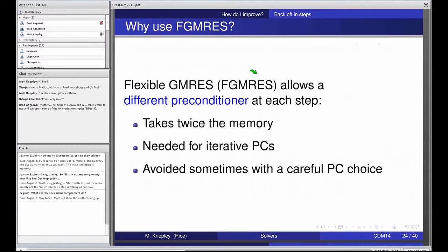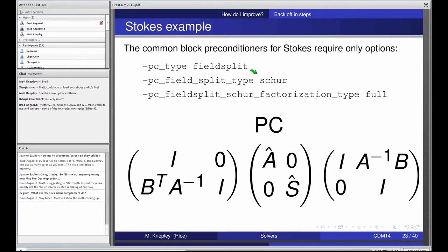And that is what I suggest you do for your initial solves for fault problems. You select a field split preconditioner, Schur complement split type, Schur factorization method full. You use an LU on A, and you use a Krylov method with a very low tolerance for the tractions, and then you'll get the exact answer to the full problem. And we'll do that in our examples.